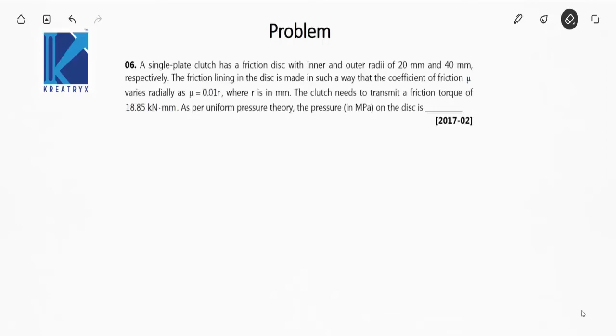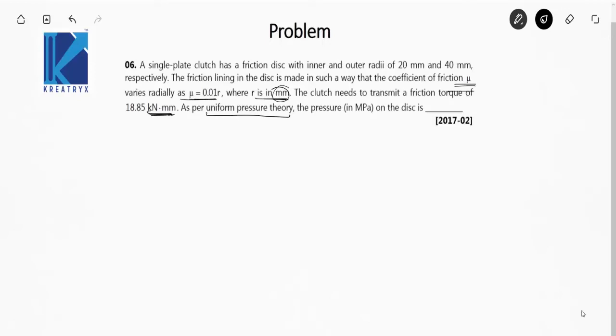A single plate clutch has a friction disc with inner and outer radii of 20 mm and 40 mm respectively. The friction lining in the disc is made in such a way that the coefficient of friction mu varies radially. So now the coefficient of friction is varying with r, where r is in mm. The clutch needs to transmit a friction torque of 18.85 kilonewton mm. Check the units, kilonewton mm. As per uniform pressure theory, the pressure on the disc is...